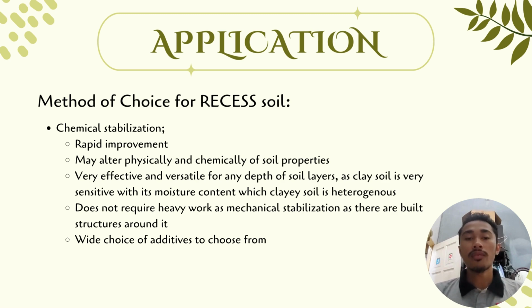It is very effective and versatile for any depth of soil layers, as clay soil is very sensitive to its moisture content, and clayey soil is heterogeneous. This means that clayey soil is unpredictable in its layers. Furthermore, we only have 3 meters of data on recess soil layer strength, and we only have a shear strength value, so it is relatively insufficient for us to choose any specific method to use in this recess location.